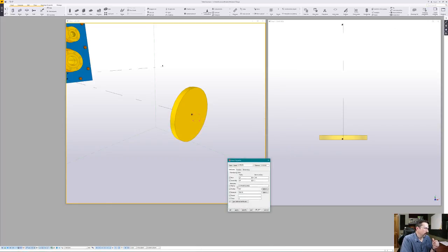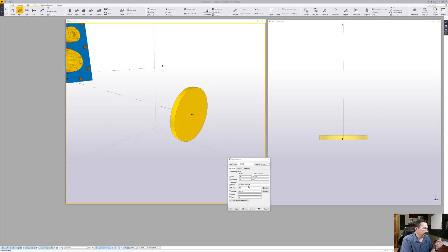So we're going to take our same beam properties that we had here, and I'm going to pick up the beam command and get that activated. Then I'm going to set my diameter to be, and I'm going to put in the actual decimal, 6.19 inches. Now, when you put in a decimal in a profile or pretty much anywhere, and I'm using U.S. imperial dimensions here, whenever I put in a profile of 6.19 inches, when I hit enter or go out of this into another field, it changes it to 6 3/16. Now, is it exactly 6 3/16 inches?